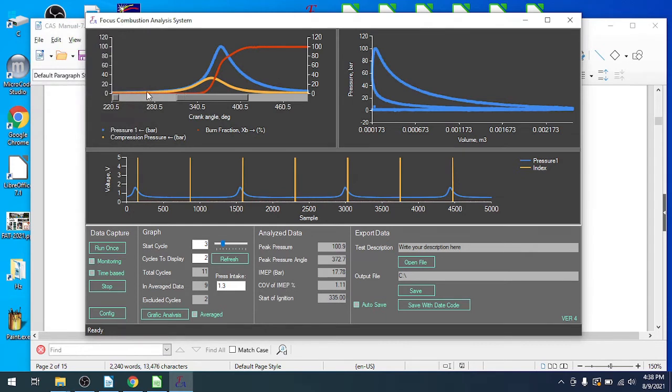Okay, so now we're back, we're set 0 to 120 bars or whatever. We have very good resolution in here. Now what I wanted to show you is we have very rapid combustion here. This is your pre-mix burning. And then we have a slower combustion later on. This is your mixing controlled combustion. Remember, we're looking at a diesel engine. And so you've got a pre-mix combustion followed by mixing controlled combustion.